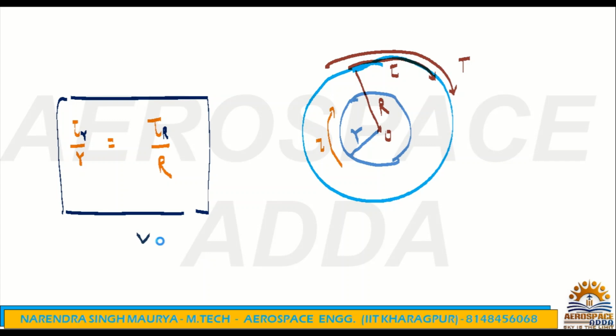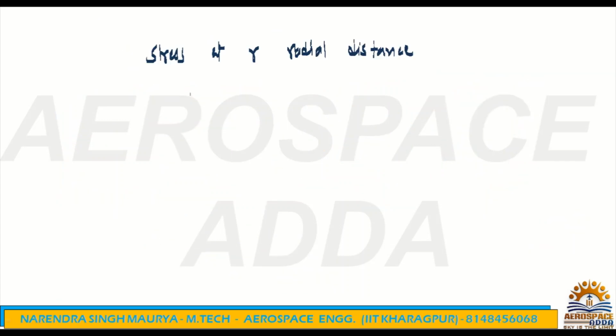So if you write tau for that small r radial distance, it's tau r. What will be this tau r? Tau r by small r is equal to tau by capital R. Just now I told you here, see this one. So small tau r is nothing but tau by capital R into small r. Yes or no? Into small r. Now this is the shear stress.